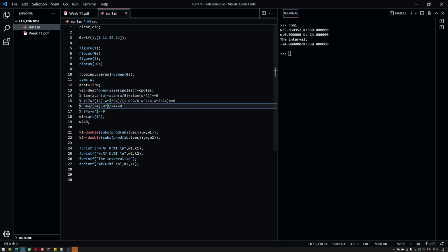If we would have had that, we needed to use that information. Since we have theta 1 plus theta 2 plus theta 3 corresponding to the angles of the vectors drawn from each pole, if we would have had any zero, then they should be contributing negative thetas, so theta z1, z2, etc. That should be negative. So there's an inverse relation between the poles and zeros, which makes sense. If you sum the poles up, you have to subtract the zeros.